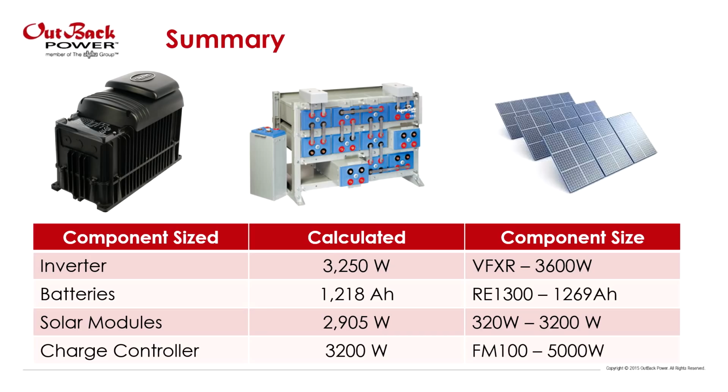So that's pretty much it. We did that ballpark, and like I said, there's so much more to this. I wouldn't actually choose components based off of this. This is more to understand what you are sizing and why it is important. And like I said earlier, the inverter was the only thing we used power for. Everything else was based off energy. It's so important to understand your loads and how long your loads are on.